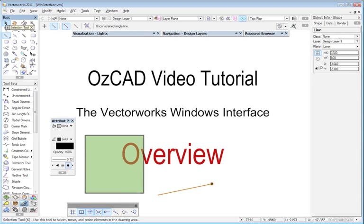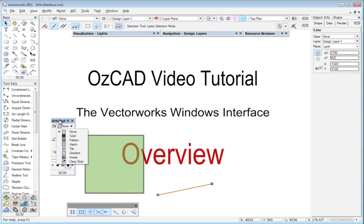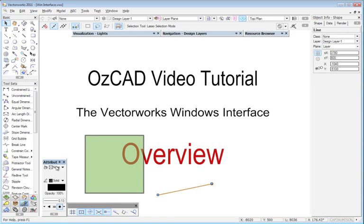Finally, when talking about the palettes, we have got the constraint or snapping palette, as it's sometimes known. I'll just move that one back down there, and this is the constraint palette here. The first constraint is snap to grid, and I would recommend that is nearly always off unless you have a specific need to have it turned on.